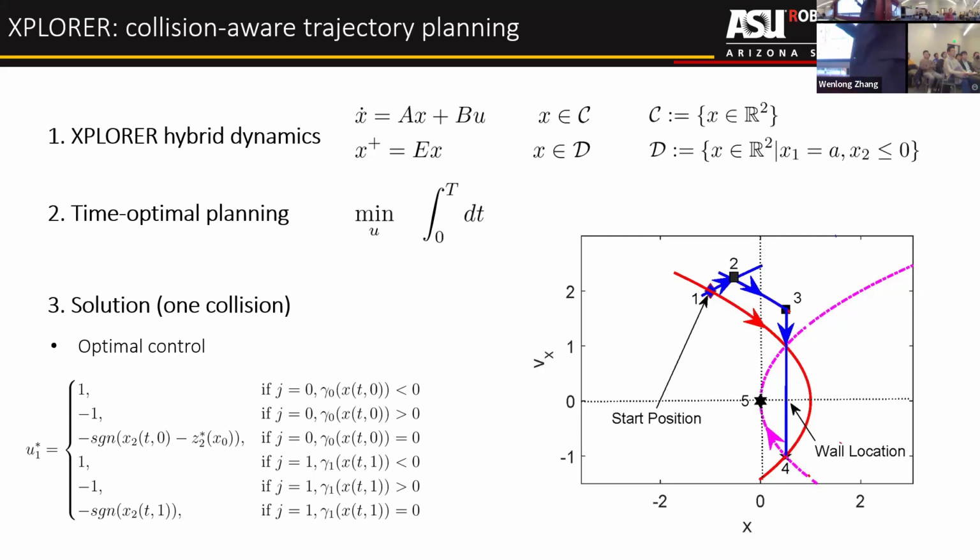If there's nothing in the environment you can collide with, then your drone essentially follows a phase portrait, with X and VX. So your drone will just slide through this parabola, and when you hit this point, you go to another parabola and then you go here, right? You probably do +1 for all of these and then -1 for all of these, and then you do a bang-bang controller, and this is the final destination, and this is the time optimal trajectory you should take.